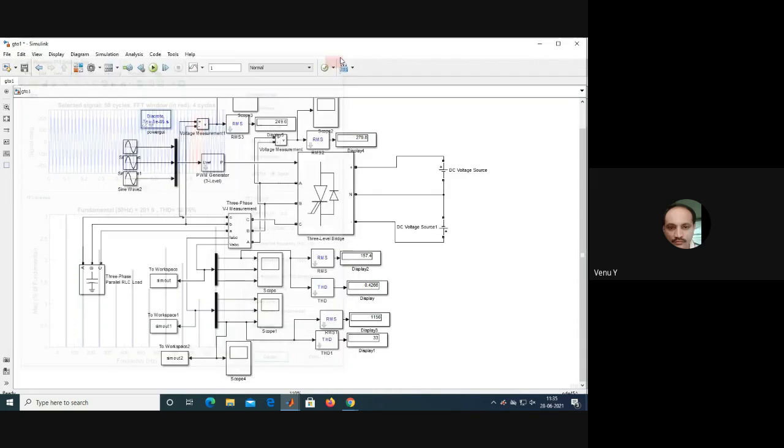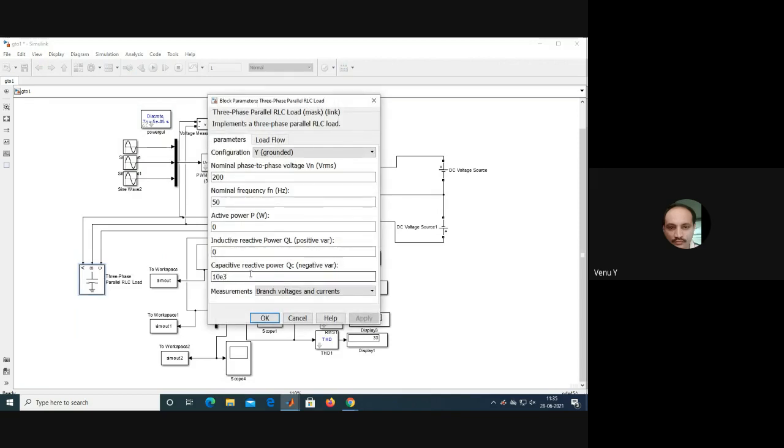So from this you can understand very easily that the STATCOM may be more suitable for inductive loads. It also supplies the capacitive load, of course. But THD content is very high due to switching. And this is inductive and capacitive load. Let us reduce one of them, 5.